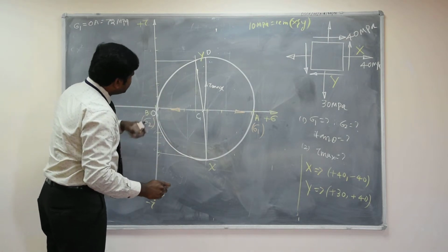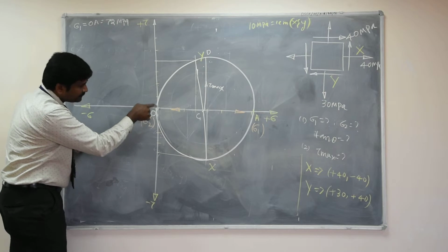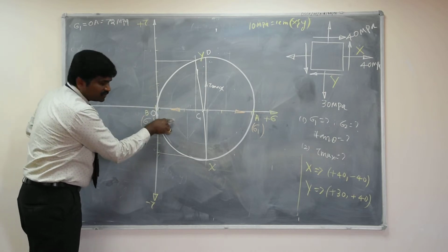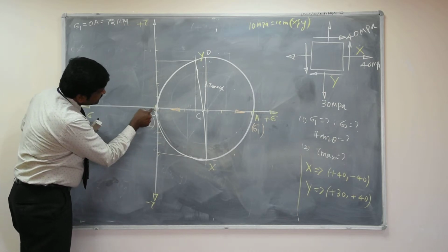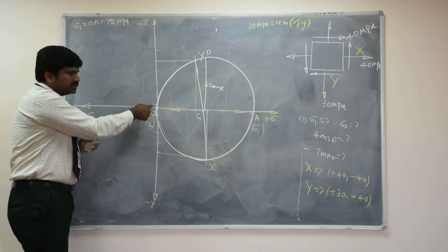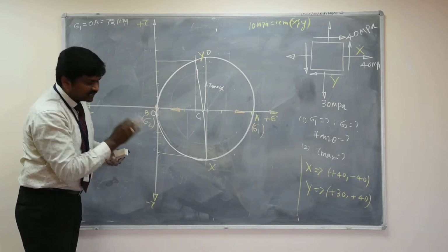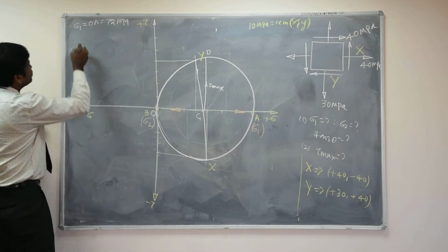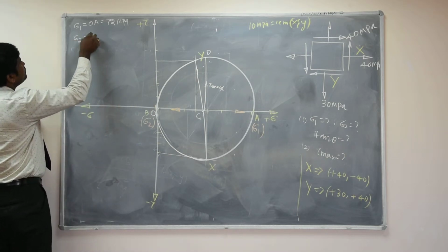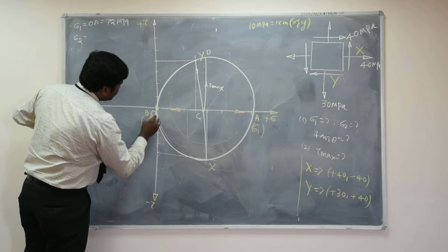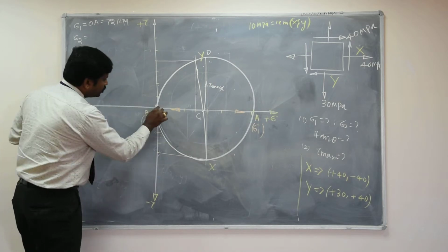Then what is the minimum principal stress? Minimum principal stress is here. In this diagram, this intersection is taking place on the negative axis. So this would be approximately -2 or -3 MPa. So sigma 2 will be the distance O to B. It is O to B.